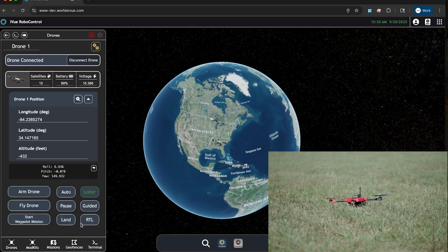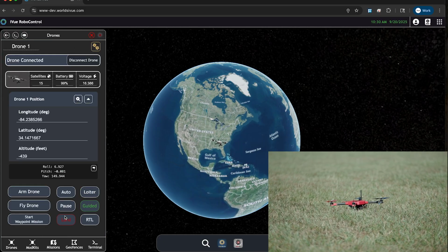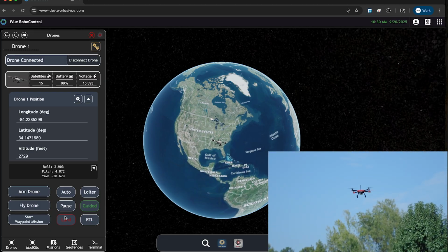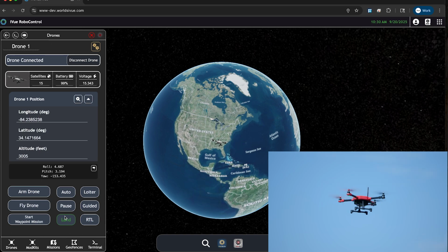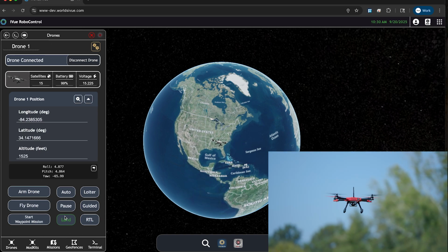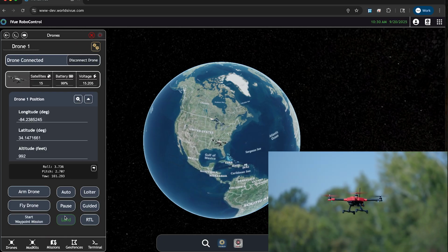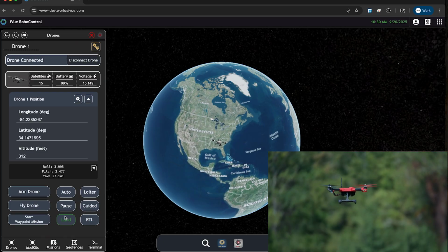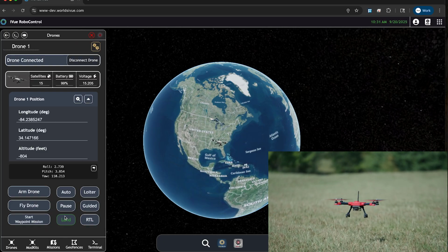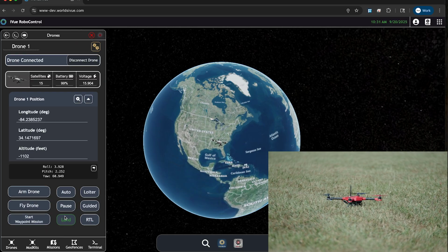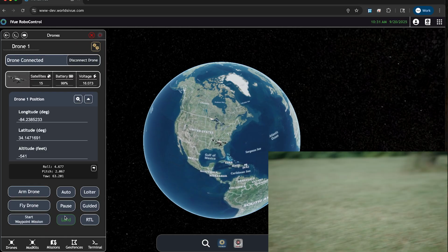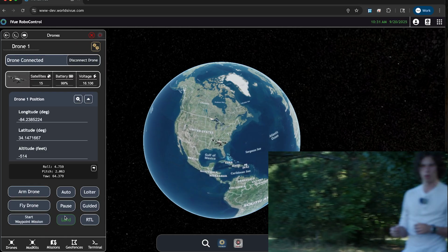All right, I'm selecting launch, ready to select land at any moment, and yeah, it's still definitely continuously rotating. And I don't seem to have controller input. Given now I'm in land flight mode, I should still have some controller input, and it does not look like I have any. So yeah, it seems like iVue RC, our software, is continuously sending controller input even when there's no controller actually connected.